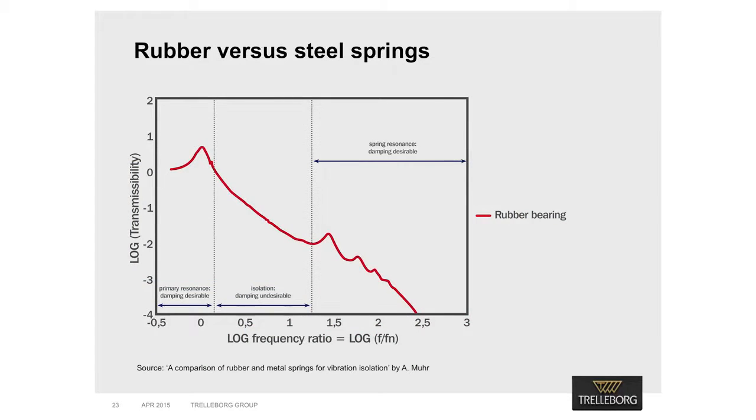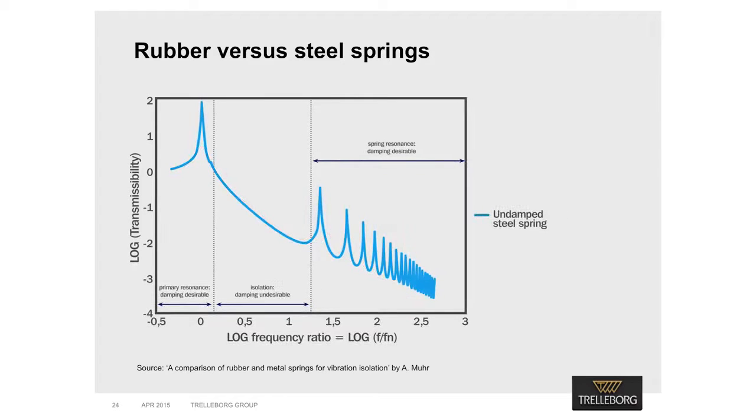Rubber bearings offer the advantage of a small amount of intrinsic damping. Although damping slightly reduces the degree of isolation, some damping is desirable to control the amplitude at primary resonance. This is because the broad range of exciting vibrations generally means they extend down to the natural frequency. The intrinsic damping in the rubber can be more effective than a noise stop pad commonly inserted between coil springs and the structure. Moreover, the lower active mass of the rubber bearings gives a broader frequency range of good isolation.